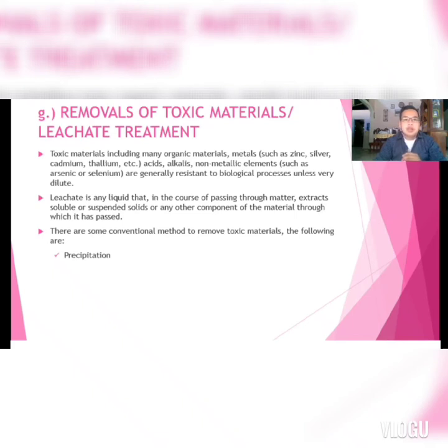The process requires addition of other chemicals, which finally leads to the generation of a high waste content sludge, the disposal of which is cost intensive. Precipitation with lime or ion exchange lacks specificity and is ineffective in removal of the metal ions at low concentration.